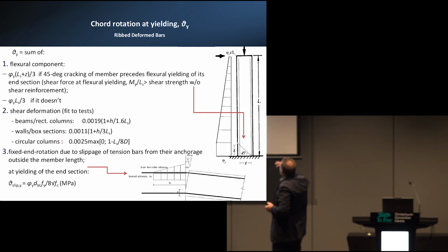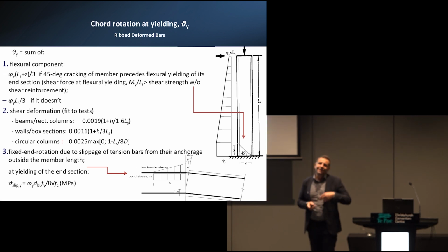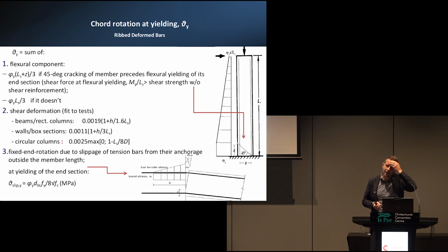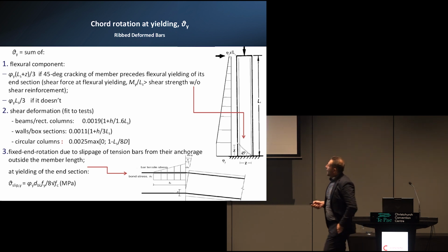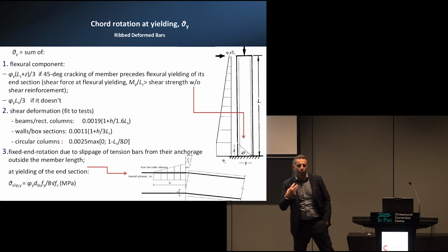There are different cases. You can have a scenario where you can even trigger the shear. Obviously, this is a very slender column, which means that in that case you don't have enough stirrups, and that is probably more the case where you have to consider an existing structure. And here there is the contribution of the slip, which is very similar to what we have.